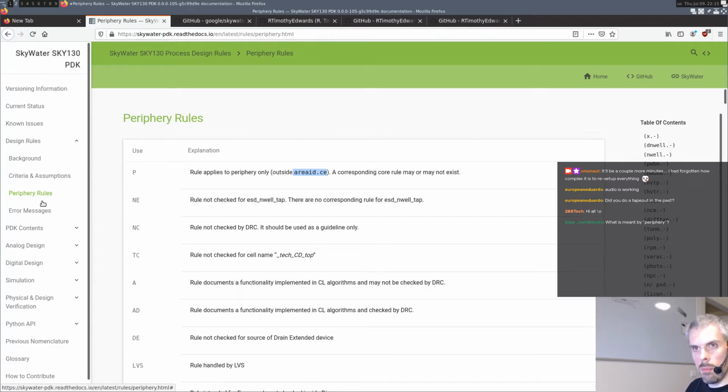What else is contained in the PDK is things like simulation models for the transistors. So they basically create the fab, they taped out some test transistors, some test features, stuff like that. They do a bunch of characterization on them, and then they provide you a SPICE simulation model that allows you to know, okay, if you produce a transistor on this process, it's going to behave like that.